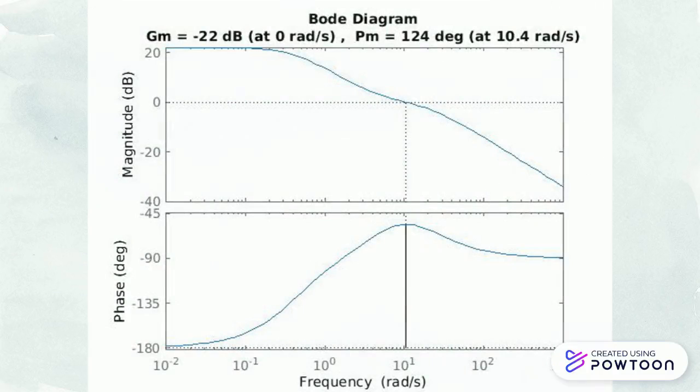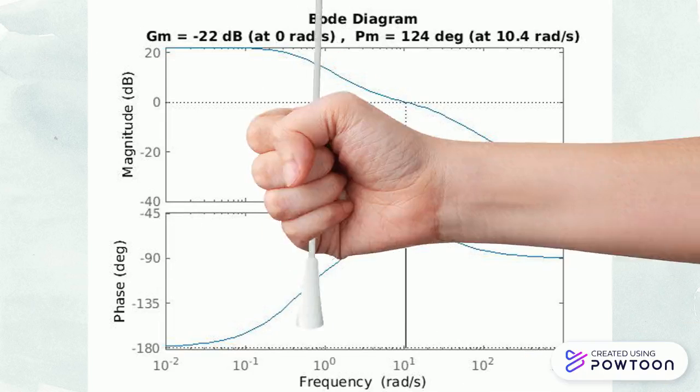We assume that the K value at first is 200. As a result, we get the Bode diagram as shown. Also, from the Bode diagram, we can estimate the values of the damping ratio and the frequency using the formula.